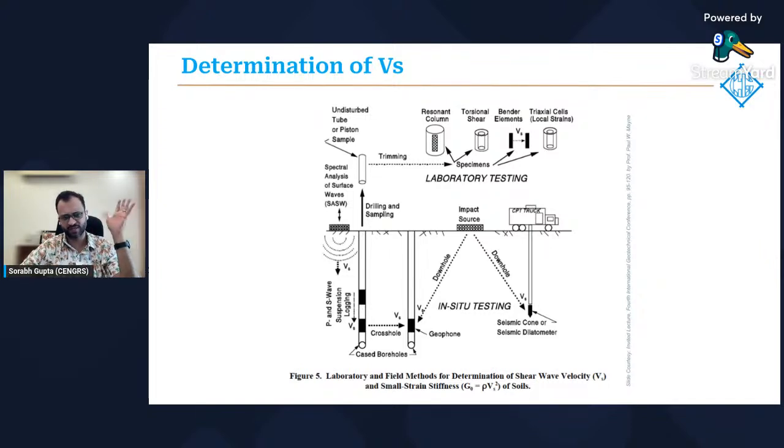Now, crosshole seismic test is great. We have been doing it for the last 20-25 years. While it's very, very accurate, possibly the only downside is the cost and the time it takes, because you have the time and cost of drilling 2 or 3 boreholes, grouting them, casing them, waiting, and then doing the testing. So it is an expensive test.